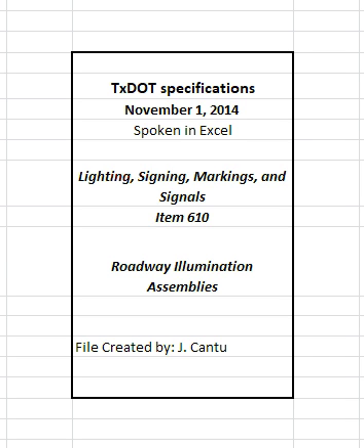2. Materials. Provide new materials that comply with the details shown on the plans, the requirements of this item, and the pertinent requirements of the following items. Item 416, drilled shaft foundations. Item 421, hydraulic cement concrete. Item 441, steel structures.